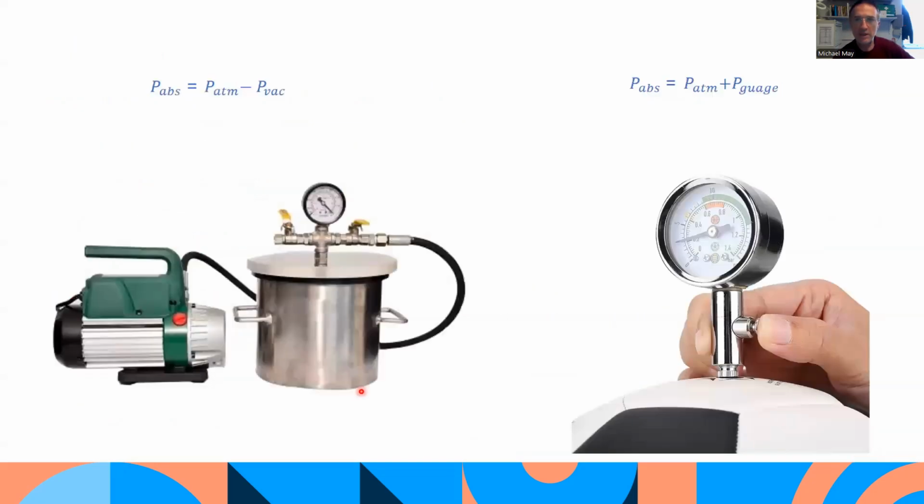If you've got a football, for example, the pressure inside the football is going to be atmospheric pressure, the same as on the outside of the ball. But then as we pump it up, you're going to measure gauge pressure on the gauge. If you wanted the absolute pressure in the ball, add atmospheric pressure to that to get the absolute pressure. I think generally soccer balls are pressurized up to about one bar gauge.